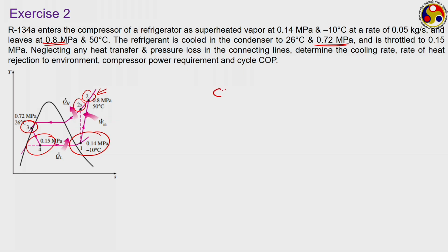Again I am giving you the final value, COP for this case will be equal to 3.93. So, COP has decreased marginally, but the Q dot E, that is the evaporation load, or I should say the cooling capacity, that has also come to 7.93 kilowatt. So, that has also changed compared to the previous value. You please do this simple calculation to get these numbers on your own.